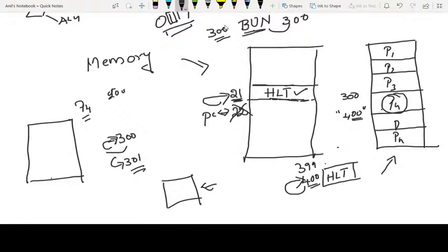If the control goes to the next location, then we will come out of the halt state. Next sequence of the instructions will get started. Next sequence of the instruction will start its execution. When we want to halt, we will use the jump to the same location phenomenon. I hope you got it. Okay, so this is all about halt instruction.